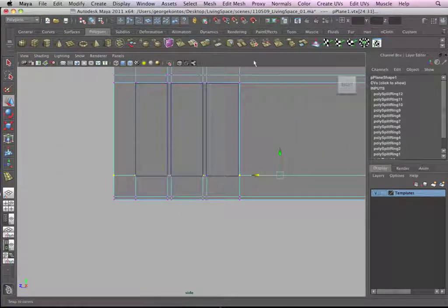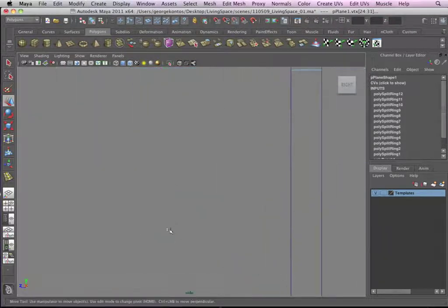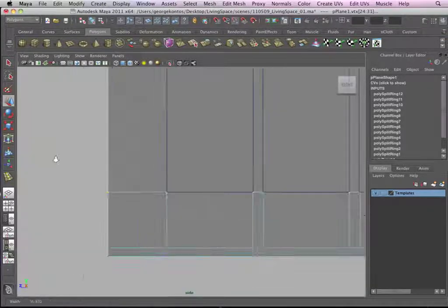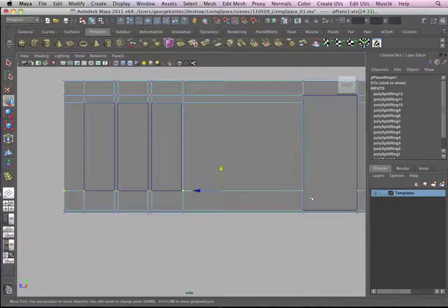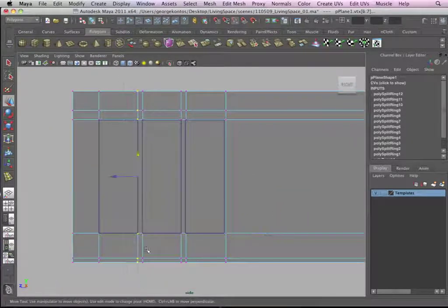Let me turn off the snap tool. So I'm going to activate this time the Y axis, so it's yellow. Turn on the snap to point, go to the point. I don't need to bring it manually. I go to the point, since the axis Y is yellow, middle mouse button, hold down and draw around the point, and everything is going to snap to that exact edge. I'm going to do everything. Turn off the snap tool.